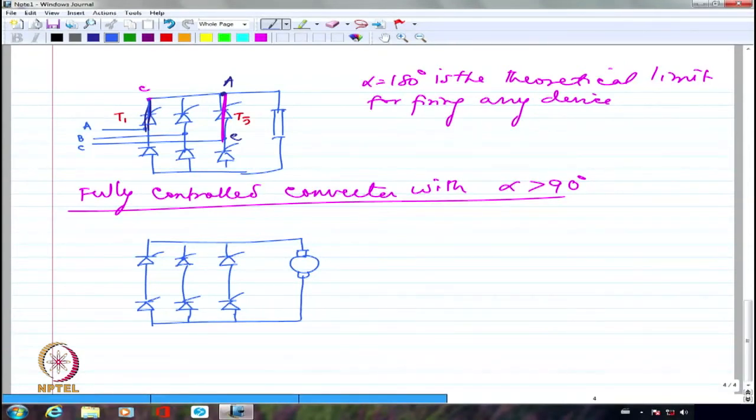Voltage is essentially going to decide what is the speed, and current is going to decide what is the torque, okay? So torque is proportional to IF IA, and EB is proportional to IF. If I forget about flux, I write in the form of field current IF omega. Okay. So obviously, I can say the voltage is going to decide the speed, and T is going to be decided by the armature current under constant excitation. Fine.